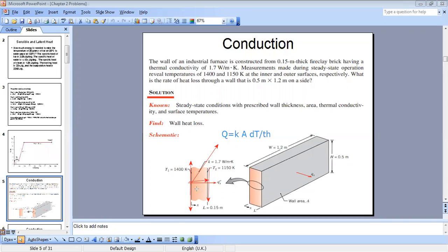And also the thickness here is much smaller. So lower is the thickness, higher is the rate. So in all cases, the dominant direction will be this one, because in this direction you have large variation in temperature. And this large variation in temperature is taking place for a very small thickness, which will increase the rate of conduction. So here it's good to consider that it's 1D conduction, because the temperature variation is nearly in one direction, which is characterized by a small thickness.